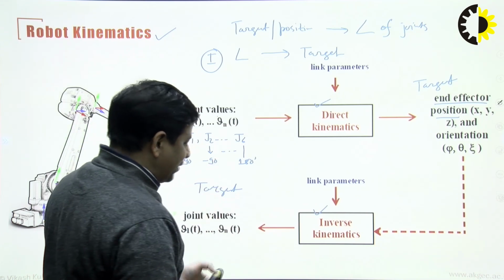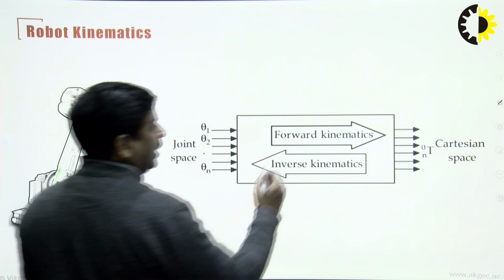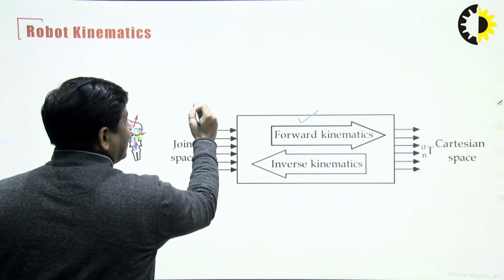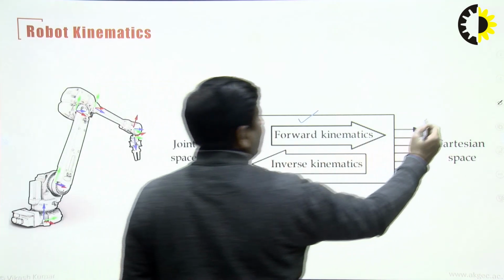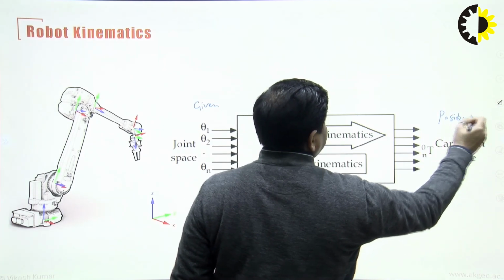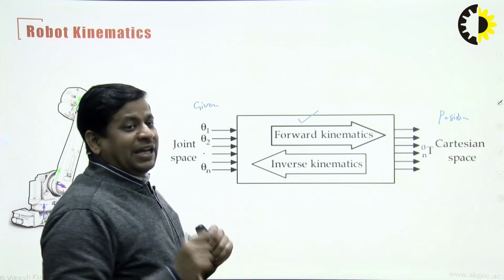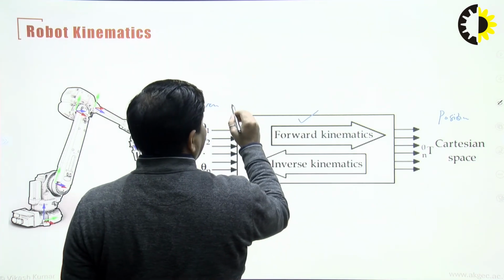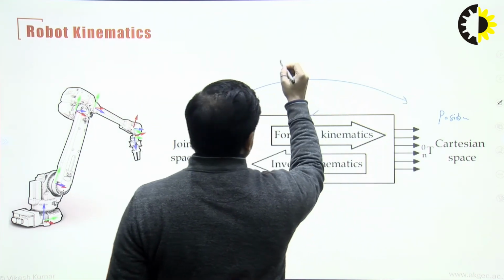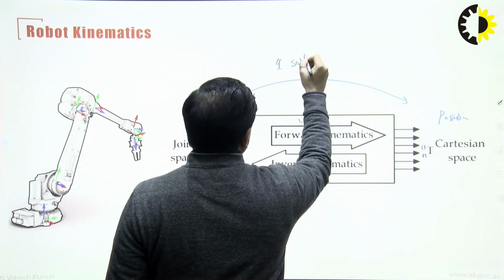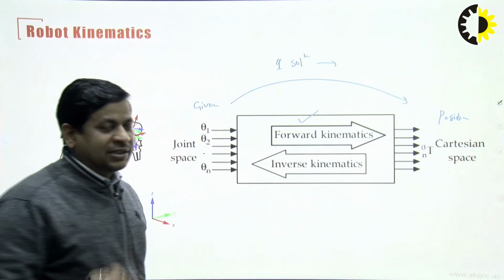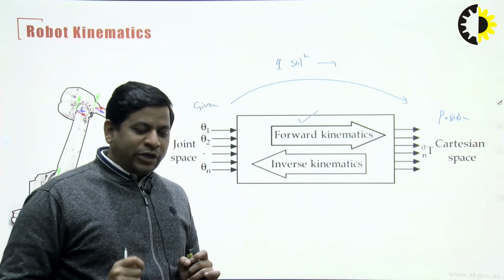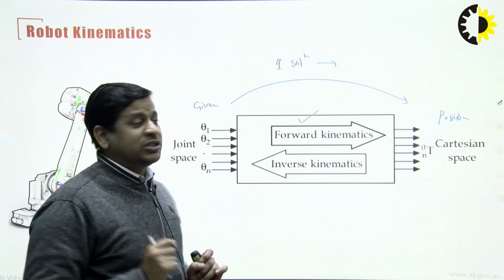So what I am trying to say is, if we are following forward or direct kinematics where the angle is given and you have to find out your position or target, then whether one person or n number of persons operate the robot, one thing is similar: only one solution is possible in the direct kinematics case, because you cannot play with the angle. The angle is fixed, so every person who operates the robot will always achieve the same position.